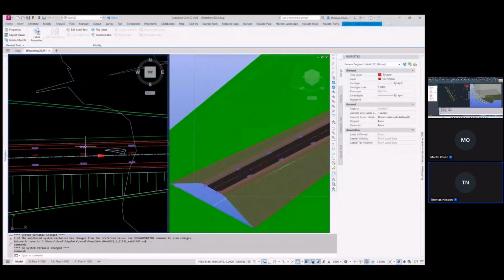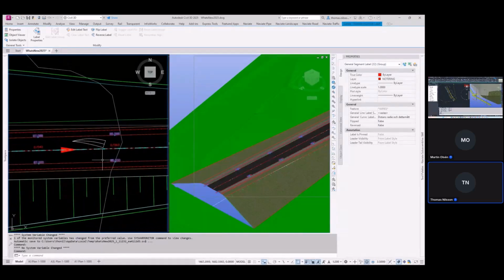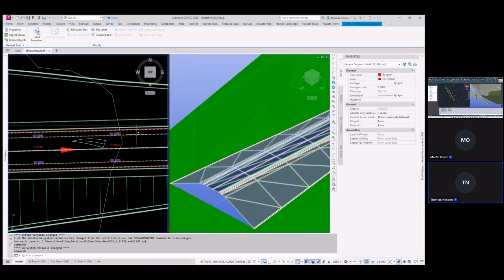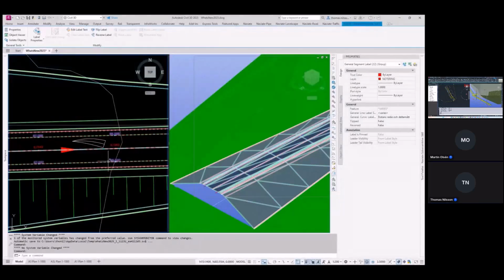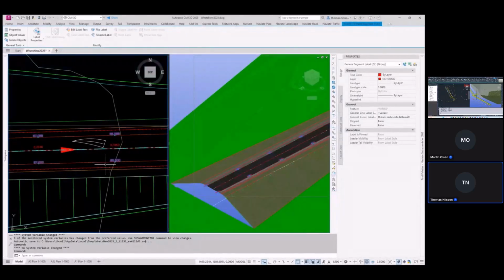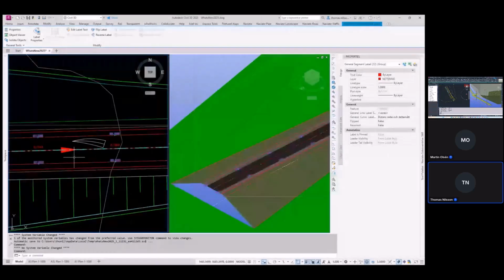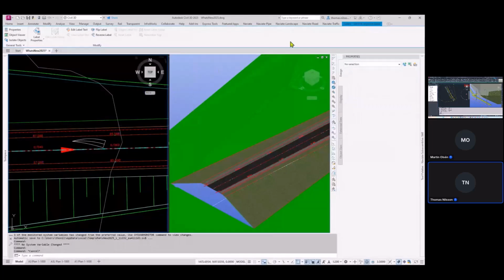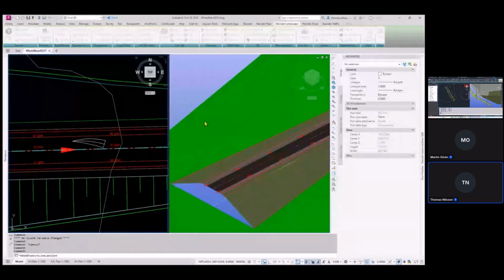hopefully, you know this command that we've had for ages to insert feature line labels on feature lines and removing labels that do not match a certain interval. Civil inserts labels on every vertex. If you have a corridor with stationing, varying stationing, maybe 5 meters, or added stations from alignment and profile starts, and so you're going to have a lot of labels to remove. We have that feature for the function add feature line label group